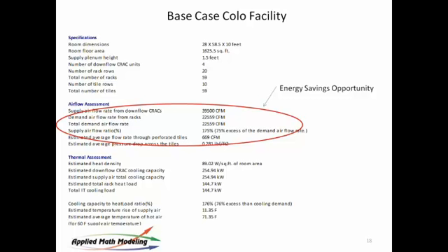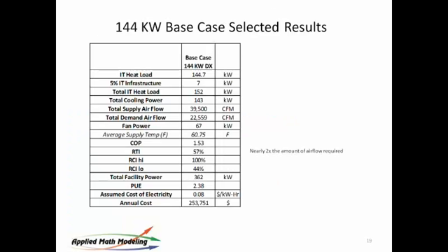And that's already going to be a problem, and that's your opportunity, first off, for improving or saving the energy in the room. So here it is in a simple matrix form, and you see the RTI is 57%, which is the ratio of those two. It again is the required over the supplied, so it's a ratio less than 100. The RCI high is 100%. I've run a simulation here already, and I've done the calculation, and the RCI is 100%, which means none of my racks are out of spec on the hot side. On the high side, right. Right, but look at the low side, 44%.